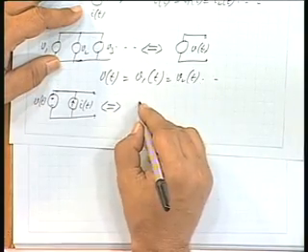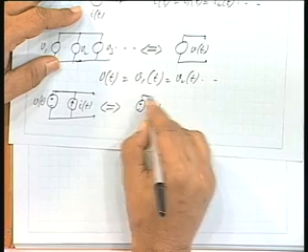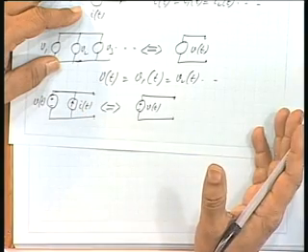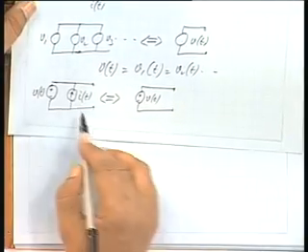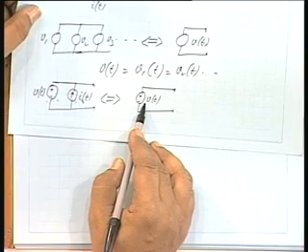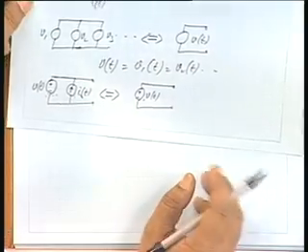So, this is equivalent to just the voltage source Vt. So, current source is redundant here. Current source does not have any role to play, it does not give any additional voltage, all right, because the terminal voltage must be same. Okay. So, for a parallel connection of voltage source and current source, we can replace this by an equivalent single voltage source of the same magnitude Vt.